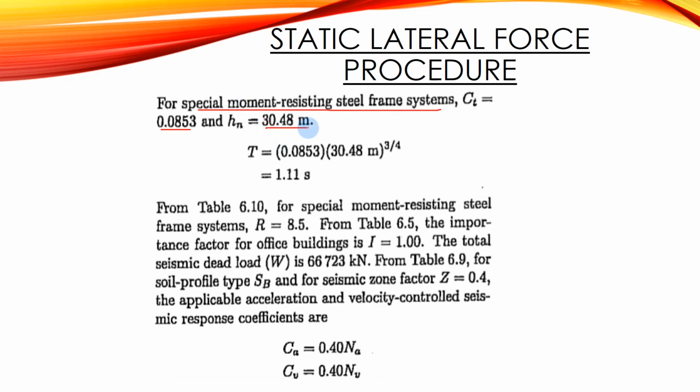Then this is the total height, 30.448 meters. Substituting the values, we have the period T of 1.11 seconds. From the NSCP table, for the special moment resisting frame, R is 8.5.